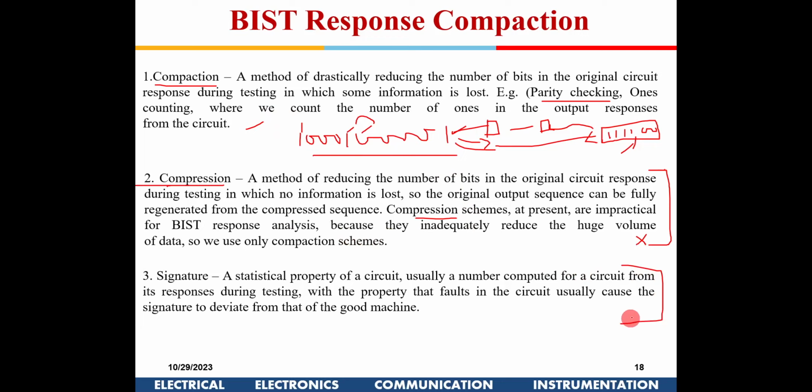So what is done in today's VLSI chips is something known as signature. This will finish off the analysis fast, as the test vectors are being applied. The data will keep generating a signature, and at the end of the entire test run, the signature will be matched with the signature generated from a fault-free circuit. Only if there is a fault do you then dissect the entire set of test vectors into small subsets, and try to find out where the fault is.